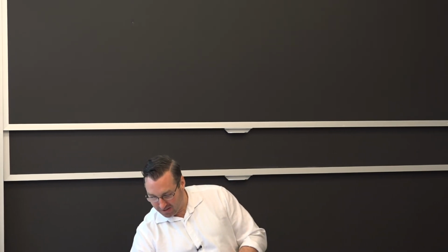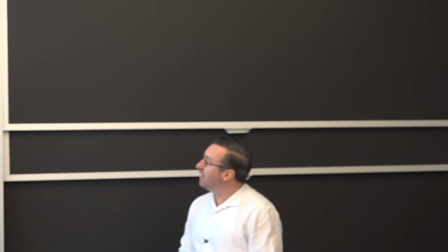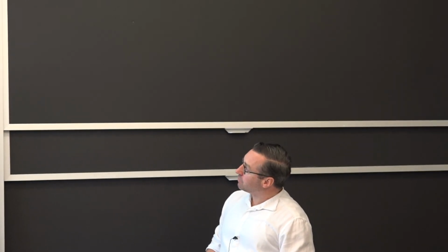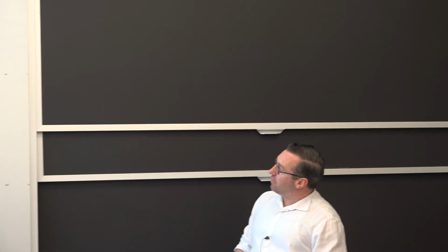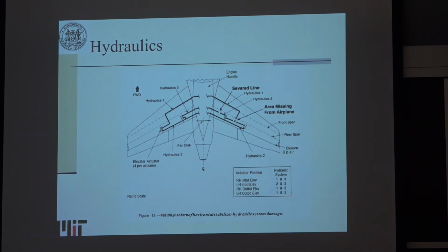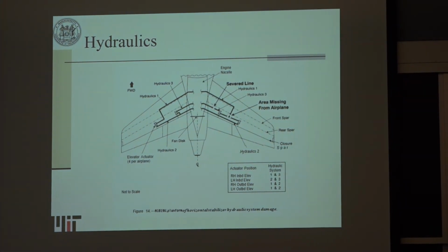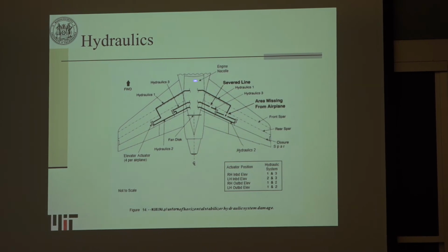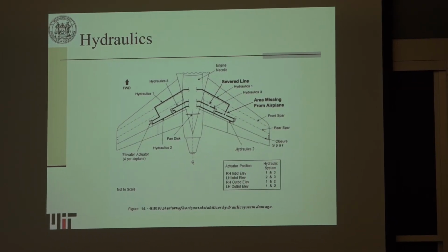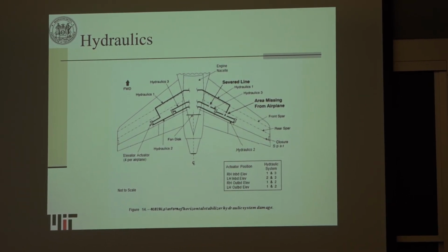And what we'll see in the slide after this is related to the hydraulics. When the rotor fractured, the loss of the disc as it came uncontained through the engine severed 2 hydraulic lines, and the actual force of the fracture caused the other hydraulic line, not in the near vicinity, to stop operating as well.